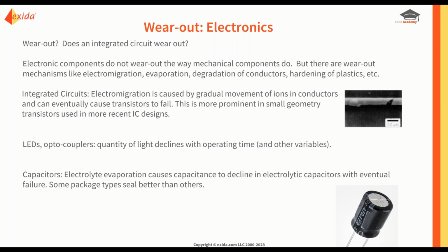Electronic components do not wear out the way mechanical parts do, but there are mechanisms like electromigration and evaporation, degradation of capacitors, hardening of the plastics, insulation degradation, and whisker growth between conductors on a printed circuit board. Now, that was real bad news when lead-free solder was introduced, and I know it's a whole lot better today, but I am told by an expert that I talked to earlier this week that it does still exist.